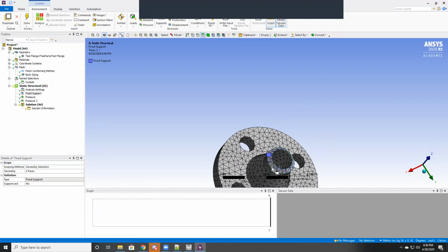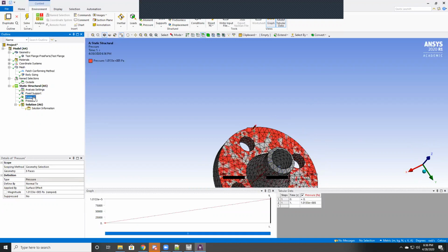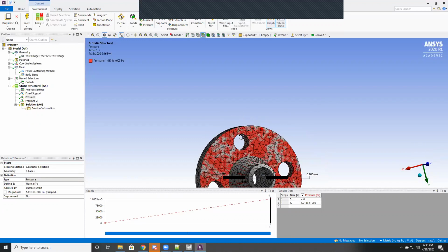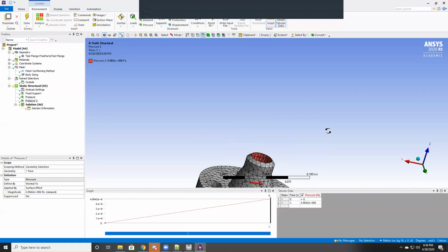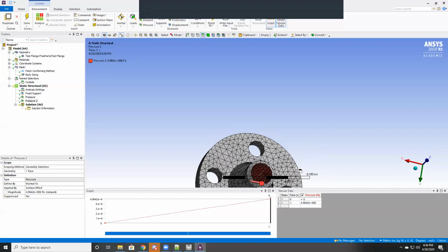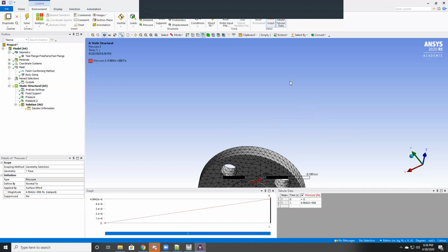We've also got a fixed support on this welding point. We've got pressure being applied to the outside. Usually this atmospheric pressure won't make a big difference at most fluid conditions, but just to be thorough, we can add it in. It could hide problems that already exist, but it's worth adding anyways. And then the interior pressure of the actual fluid in this flange.